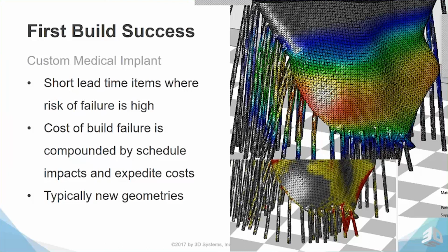Can't forget that there's a lot of post-processing that needs to be done, and you can see the amount of column supports that are on some of these parts. So this is a hip. The cup is on this left portion, kind of this darker red portion. But you can see this is a displacement, so you're going to have some closing off of that, so that might be a problem if you're going to do some post-machining into that joint. Add some plastic bearings and such in there.